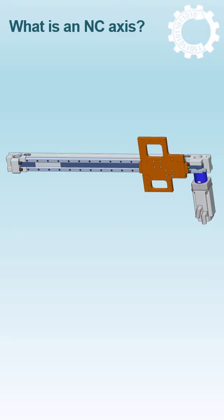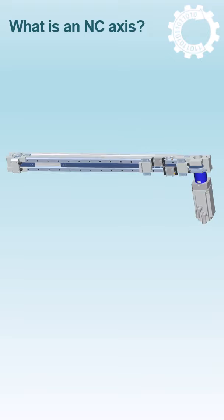On this moving red plate, a tool holder or a gripper or another axis can be mounted. This plate is mounted on dovetail slides, as one can see in this case. These can also be linear bearings or V-groove bearings. These slides are mounted on profile rail guides and can slide in both directions.